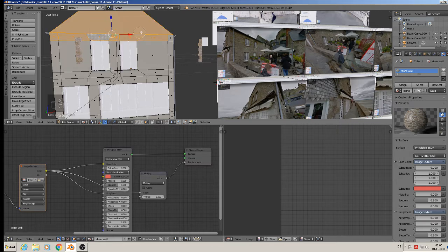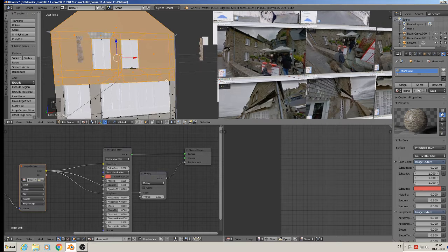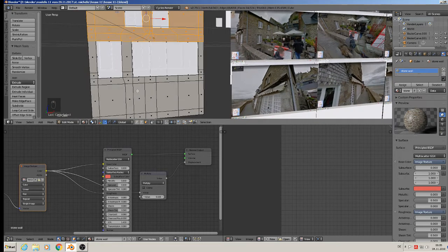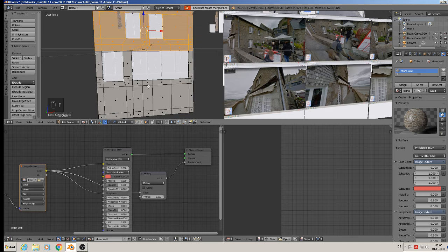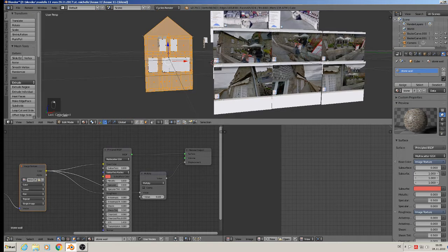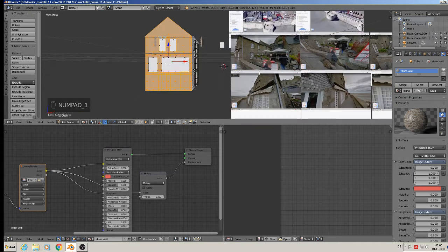Circle selection is the fastest way to select that, because it's free and not like border selection. You must make correct borders to get it all. Circle selection is a wonderful way for that. You can roll the middle mouse button to make it bigger or smaller. That is fine, so you have a fast result.